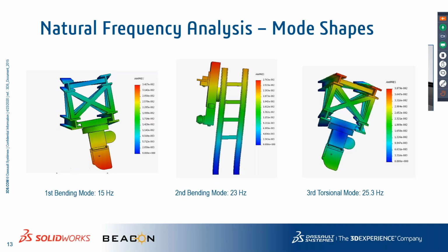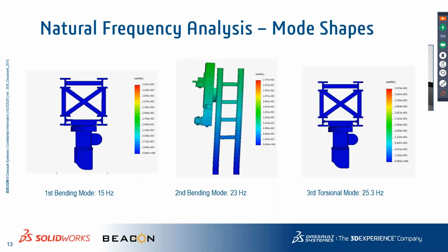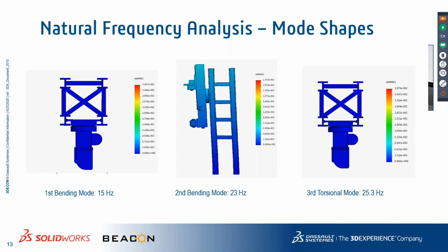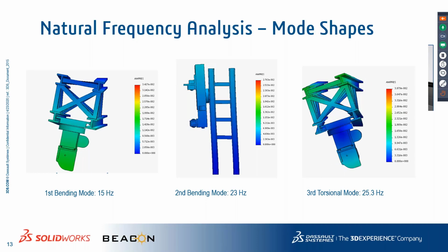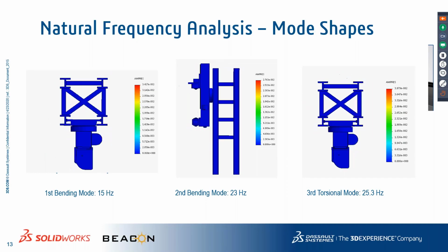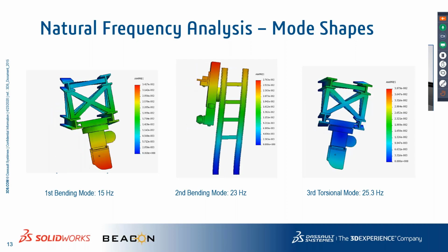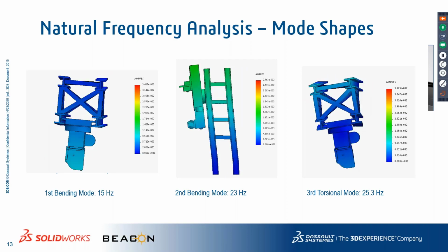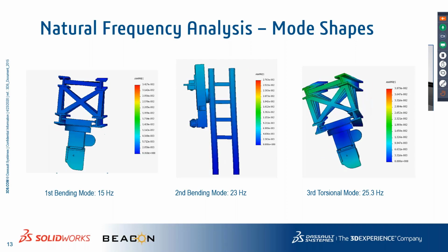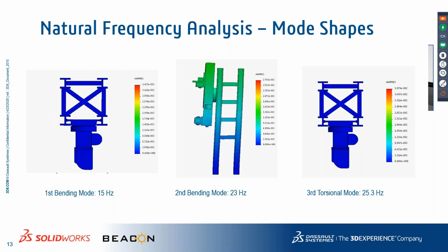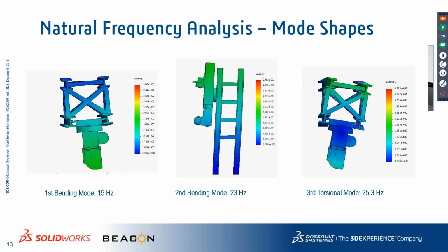It calculates the resonant frequencies of our structure, and by doing this analysis, you will be able to see whether my structure is capable of handling those vibrations, or whether I need to add some extra stiffness or make some design changes before proceeding to the manufacturing process, to avoid failure of your structure due to vibrations.